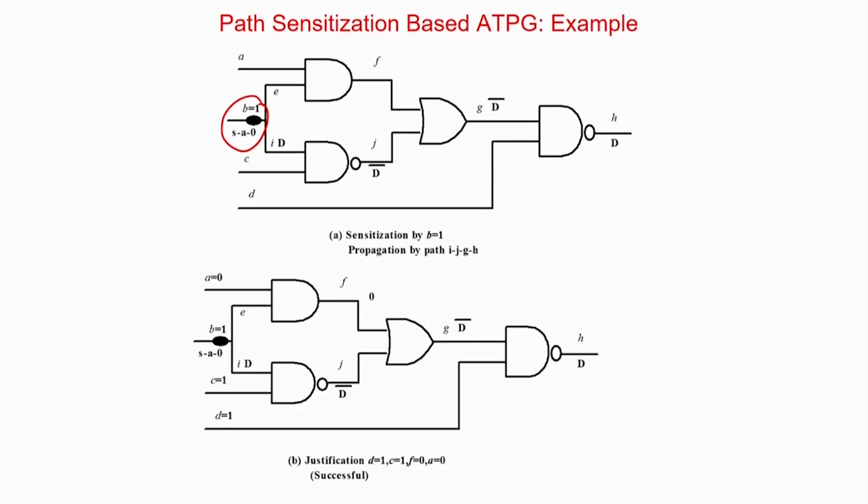So when you will be studying optimization, we will see how to handle this with higher level fault model and higher level of test. But anyway, let us come back to the basics. So now A equal to 0, B equal to 1, C equal to 1 and D equal to 1. So this becomes your test pattern to detect this fault, and the output is D. If the circuit is normal, that means this stuck-at-0 fault is not there, you are going to get the answer 1. If you get the answer 0, then you know that this stuck fault is there.